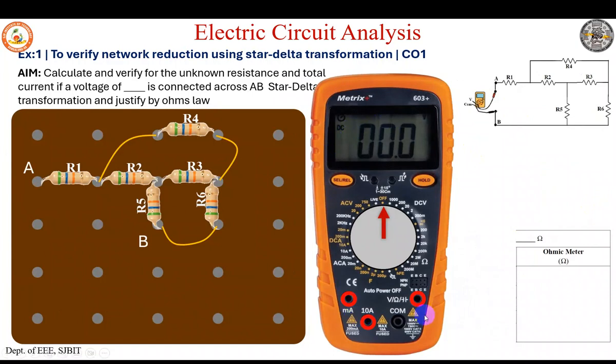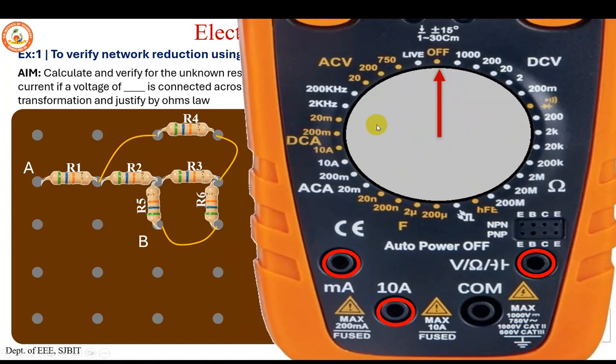So we have a multimeter. As discussed in earlier classes, this red color indicates positive, the common black color indicates the negative terminal, and we have this knob, right? So where do you see the ohm symbol in this multimeter? You see here it ranges from 200 ohms to 200 mega ohms, and you can see here it says ohms. So voltage, ohms, and capacitance. So you have to connect between common and this point. I repeat, between common and this point for voltage, ohms, and capacitance.